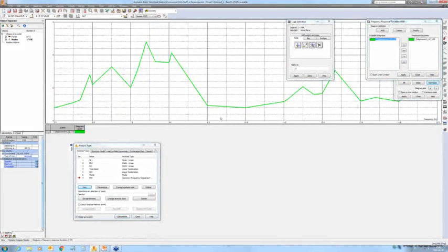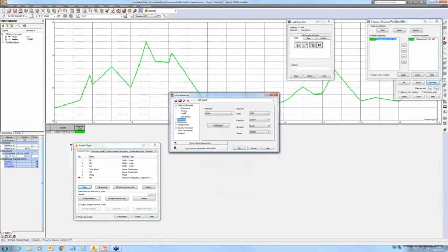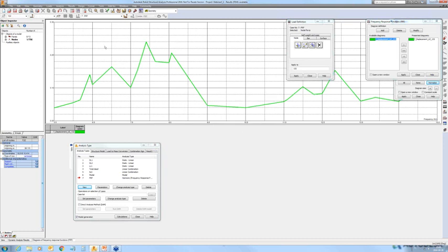Well, as you can see, because the number of divisions was small, the diagram is not smooth. But what I'm going to do at the moment, I'm going to make two changes. First of all, I'm going to change the units of displacement, the precision of the display of the displacement, so that you can see the values.